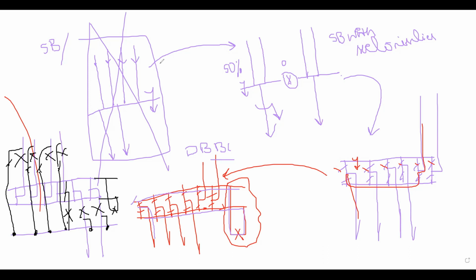Now, suppose this breaker fails. Then this power will be transmitted through this transfer bus and this breaker, and it will come to here and go to the lines out. Suppose this line fails, then similarly this power will be transmitted through this bus and will go to the circuit out. So this scheme is generally designed to maintain reliability of the breaker, not of the bus.